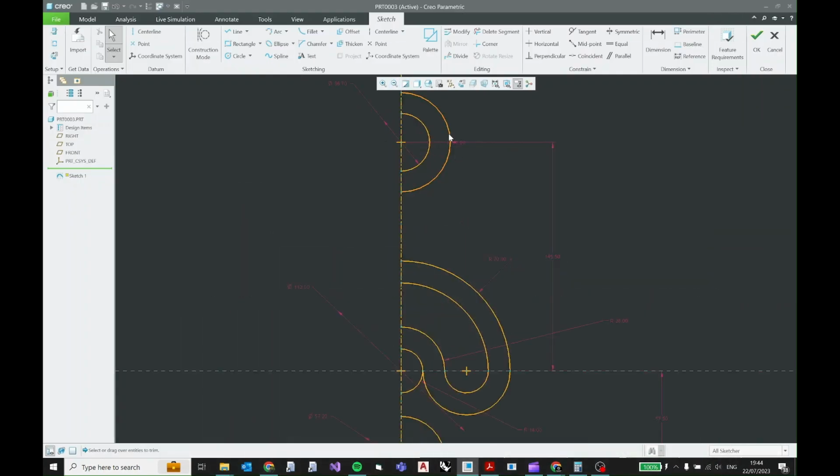So I'm gonna go over here, select the line command, point to the center of the circle, and then hover across to join tangentially to this circular arc, and then click to set the start point, and then keep vertically dragging it down so that I reach the circle, and then click the mouse button again and press escape to exit the line command. I don't need this section, so I'm going to delete that.